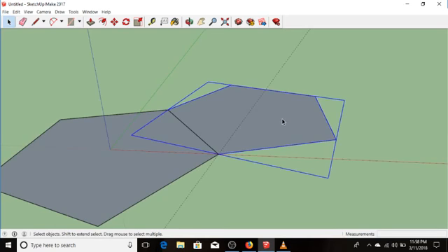Now, fancy rotation. That's the piece I want to rotate. Rather than click it there, I'm going to drag the left button to set the axis. I'm not going to drop it there. I'm just going to put it there, snap it right to that spot, then hold down the left button and choose the axis of rotation.